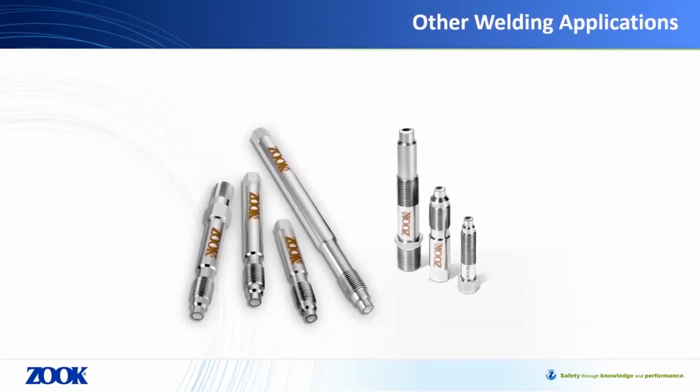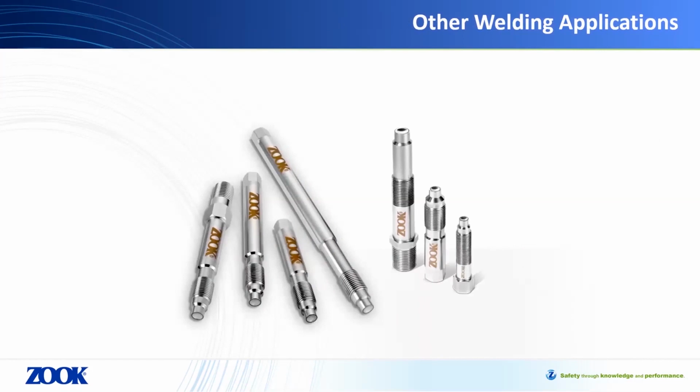Rupture discs are also commonly used in plastic and polymer extrusion processes. Due to their size, price, and fast-acting nature, a rupture disc is a fantastic tool to ensure that an extruder is protected in case of a blockage or other overpressure event.